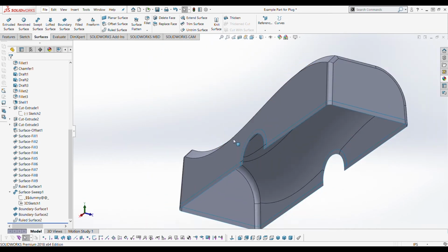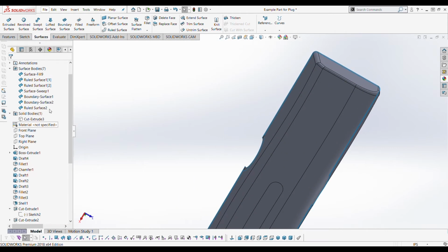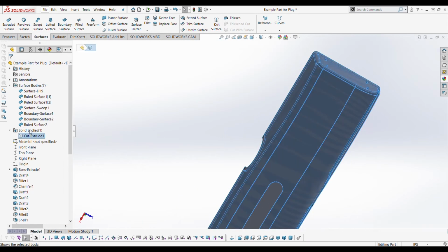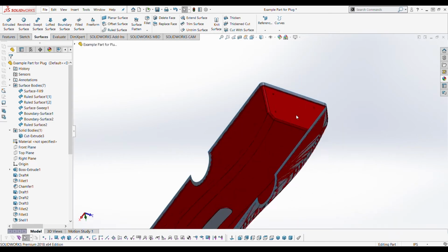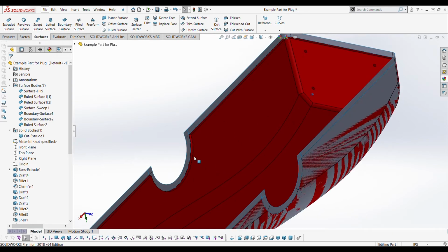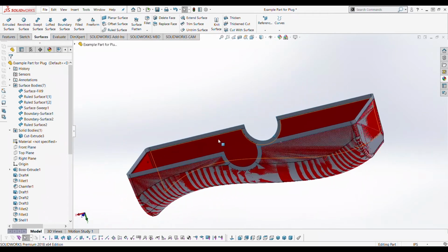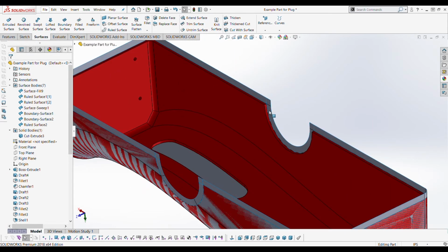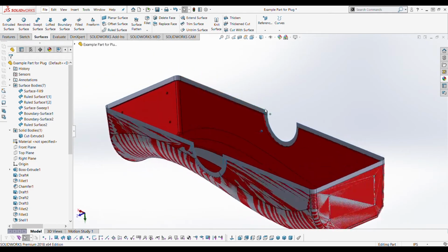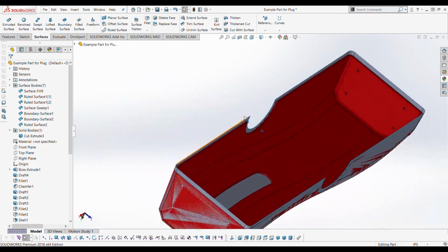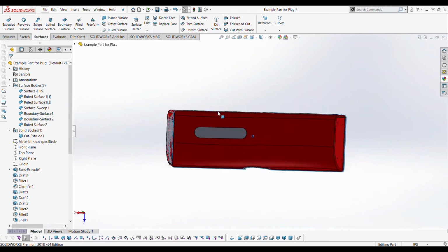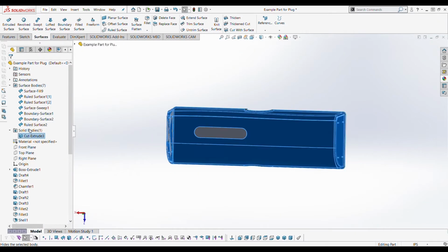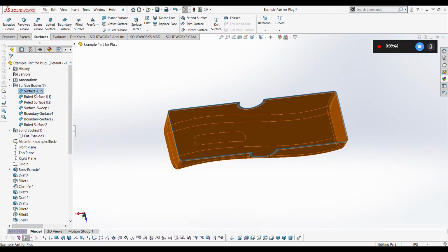Okay, so now we've extended our surface. So you'll see now if we show our part again inside of here, our mold now extends beyond it, which is going to be good for machining or even 3D printing, where you might potentially have loss of detail in the corners. We know we're going to be able to capture our entire part. So let's hide the part again.